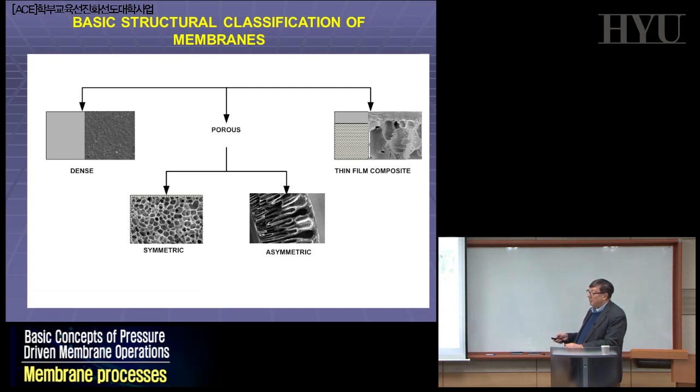Dense membranes means membranes where if there is any pore, it is a defect. You will learn in literature, in some cases, reverse osmosis, gas separation, people are still fighting and discussing sometimes if the mechanism of transfer of matter across your membranes is related to the pore size, that means sizing effect, eventually at nano level, or other mechanism, the one we will discuss, solubility, diffusivity. No pore. If there is a pore, it is a defect.